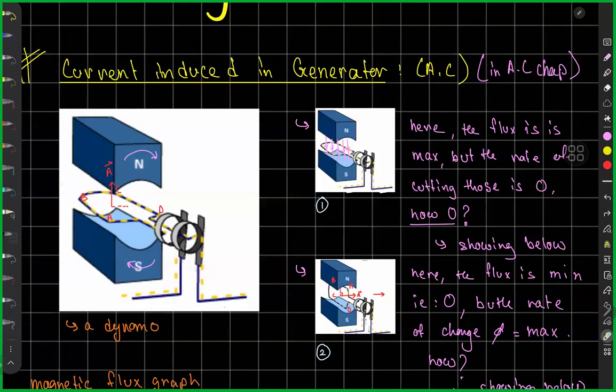It cuts through a bunch of magnetic field lines into the plane. So to compensate for that, it will induce a current in BA that produces a magnetic field that is out of the page. And if you use your right hand grip rule right now, it will show that initially it is from B to A. So our initial assumption was wrong. Initially it is B to A.